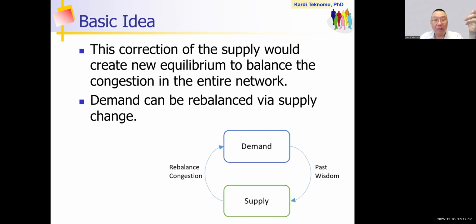So I put it in this drawing. We can redistribute the congestion by reducing the number of lanes on a specific link in the network, or deleting a link, not always increasing the number of lanes, in such a way as to lower the maximum congestion in the network. So after applying the policy, for example, road diet, road narrowing, or making a pedestrian-only zone, based on the congestion distribution, the maximum congestion of the network will be lower. But the average travel time in the network will be slightly worse.